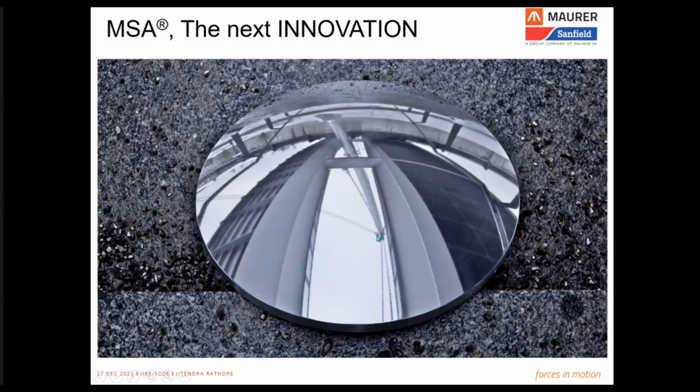The next concern for a bridge bearing is corrosion, because now we have eliminated one weak point, that is the sliding material limitation. We have a better material now, but corrosion becomes a major concern, because of the environment around the bearing, or sometimes the bridges are in coastal areas where the salinity in the environment is very high. So all in all, this leads to the degradation of the steel, and it starts rusting and corroding over a period of time. The same applies to the bridge bearings.